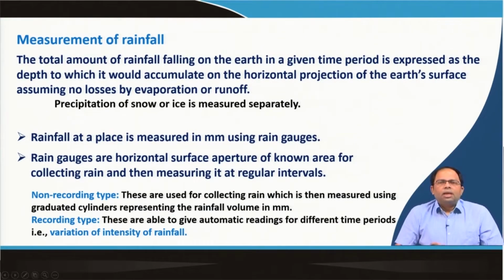This surface runoff, if we cannot control it, will lead to floods, it would lead to urban floods and so on, and we actually want to control this flow by either taking it into certain drainage channels or determining the size of the drainage channels appropriate to take this flow. That is how we should manage the amount of runoff that is generated in urban areas. But before we go into determining how much is the runoff, we first need to understand how much is the rainfall.